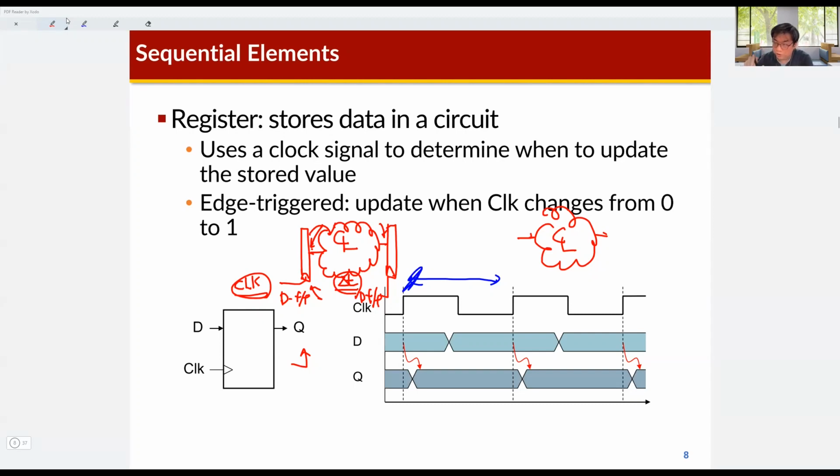We briefly know the delay, but it can be changed by many factors. After some delay, these output values are stored at the rising edge of the clock by this D flip-flop. At the next clock, this output becomes the input of another combinational logic, the next step. Okay.